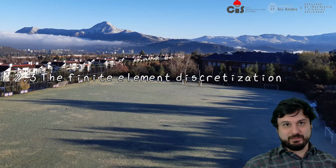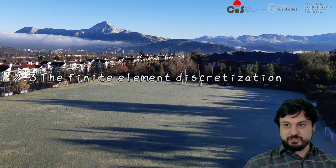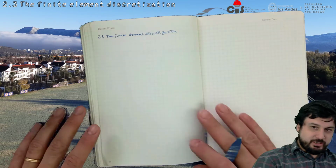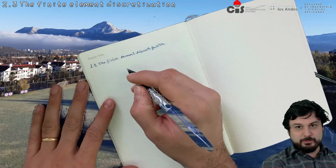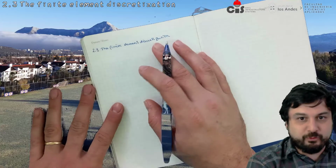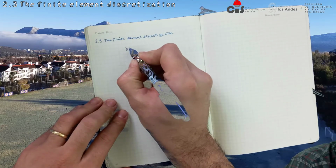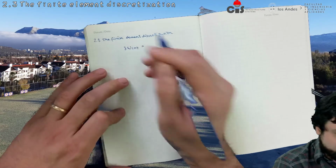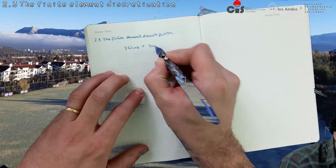Hello, welcome back. In this occasion, we're going to talk about the finite element discretization. Let's get right into it. So we left off with the statement of equilibrium stated in the sense of the weak form of the equilibrium equations. That meant that the internal work done during a virtual displacement, if the system is in equilibrium, has to be equal to external work.